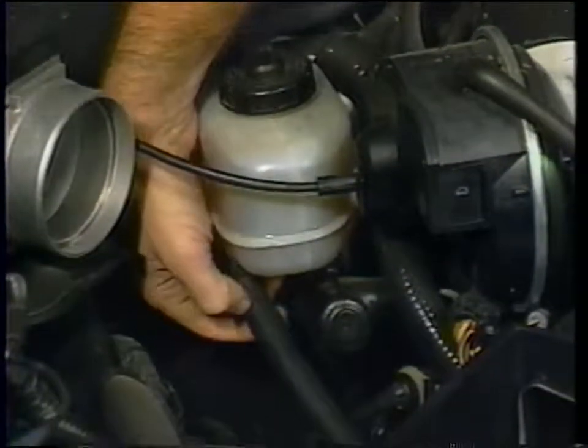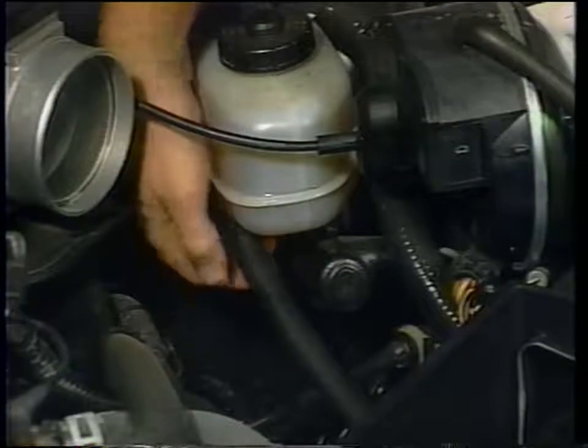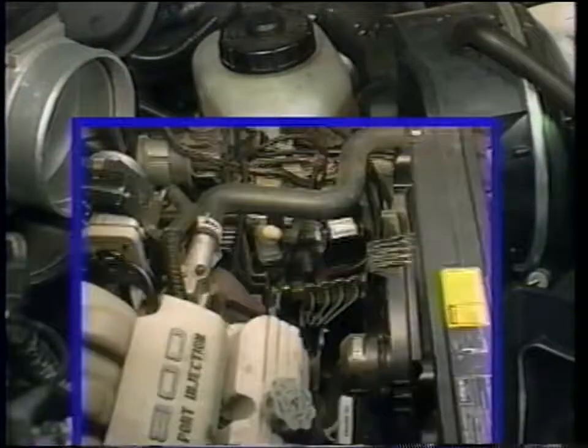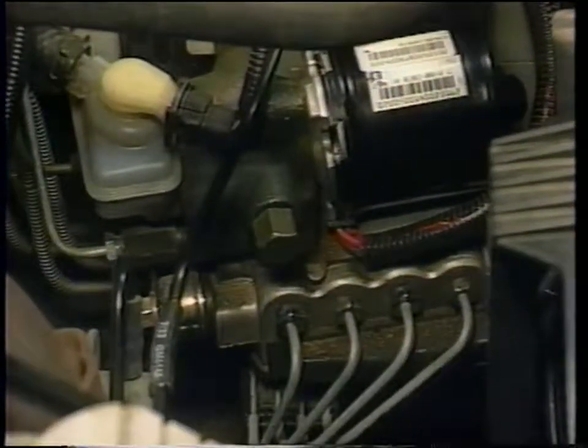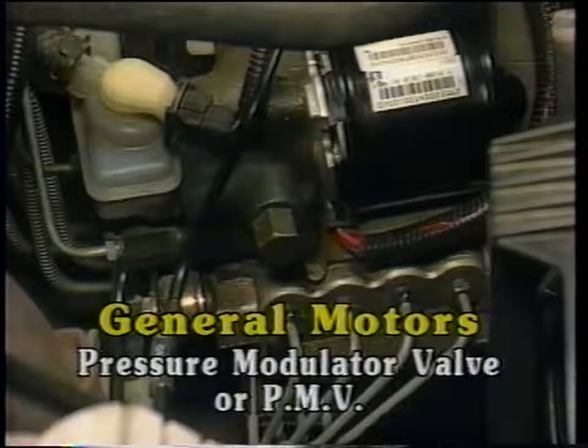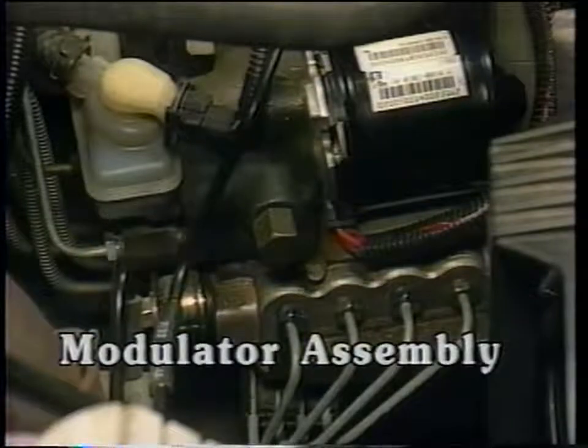The reservoir also contains a low-pressure hose that supplies brake fluid to the hydraulic modulator mini reservoir. You'll find the hydraulic modulator located in the front of the engine compartment. Ford service literature refers to it as the hydraulic control unit, or HCU, while General Motors calls it the pressure modulator valve, or PMV assembly. To avoid confusion, we'll simply refer to it generically as the modulator assembly.